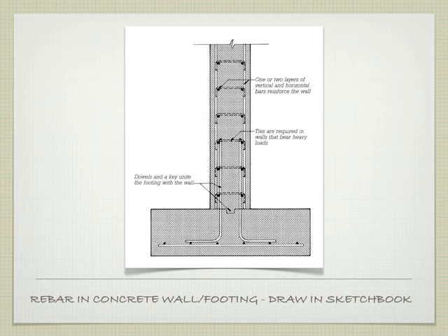So if we had a number 8 rebar, the overlap would be 30 inches. I'm not in this class going to be really specific about making you do weird calculations like that, but the fact that it's 30 times the diameter is an important number. It comes back up again and again, so chances are it's going to show up yet again down the road.